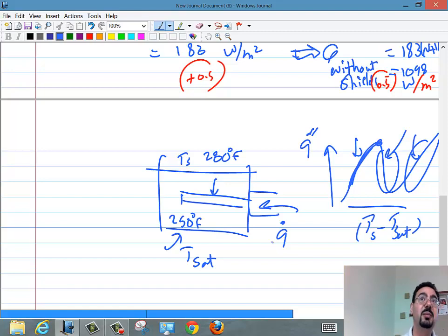The electric resistance inside just basically sends Q, right? Heat flux needs to come out, and that heat flux will determine, based on the cooling mechanism around it, how hot it will get to manage to send the same Q. So imagine this is a 1 kilowatt heater. Every second, 1,000 joules need to go into the water. The water is at 70. What's the mechanism of the heating? Natural convection of a horizontal cylinder.